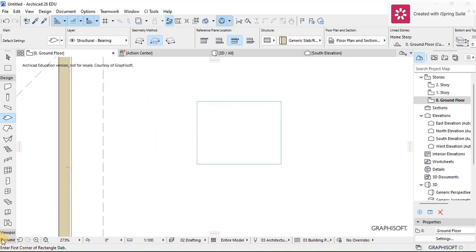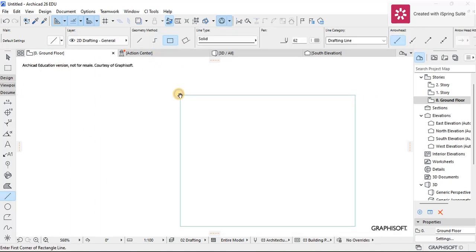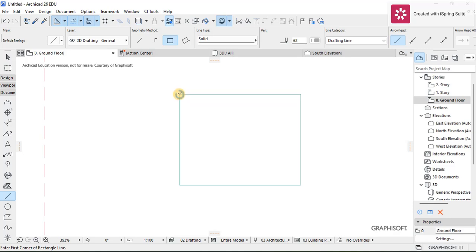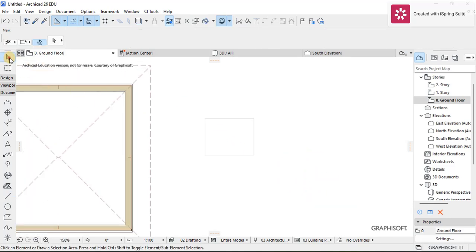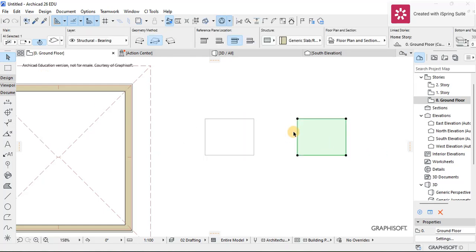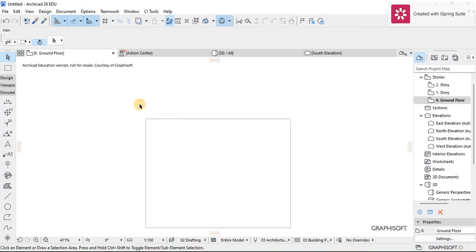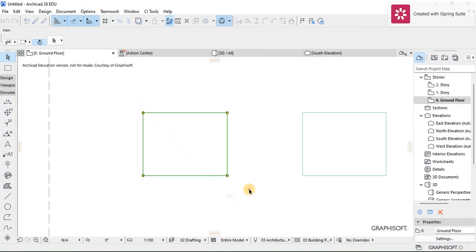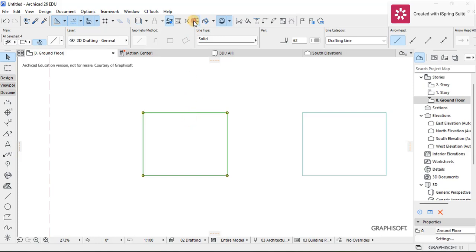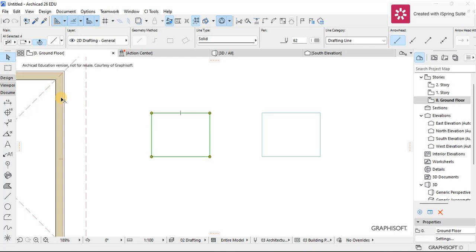To design the window, we're going to use our line tool. We're going to have to draft the design before we actually make it a window. So I'm going to draft it. Let me just highlight the slab first with my line tool and draw this and drag the slab maybe somewhere here, so that I'll be able to drag it back when I'm finished designing here. So with that said, now we have our line, which is the window outline. First of all, I want to make the thickness of the window, which is actually this thickness that is making the jamb details of the window.